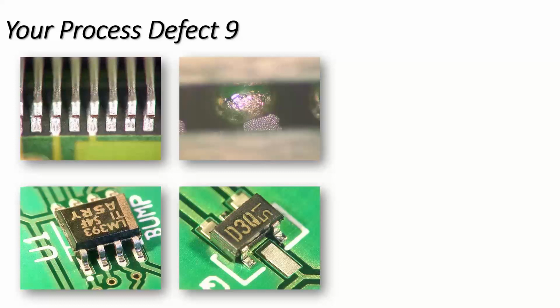Unfortunately, at some point, you may need to cut a board up. You might need to do a microsection. And the reason for that quite often is that if you're taking the liability of those failures or the consequential loss of finance on those problems, then you need to go to the baseline, which is doing the microsections.